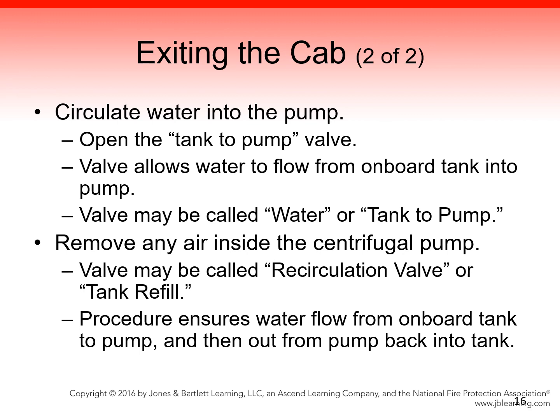Next, circulate water into the pump. Walk to the pump panel on the fire apparatus and open the tank to pump valve. This valve allows water to flow from the onboard tank into the pump. Depending on the manufacturer of the fire apparatus, the label for this valve may use different terminology, for example, water or tank to pump. Becoming familiar with the layout of the pump panel and knowing how the valves operate will greatly enhance your efficiency in operating the pump.